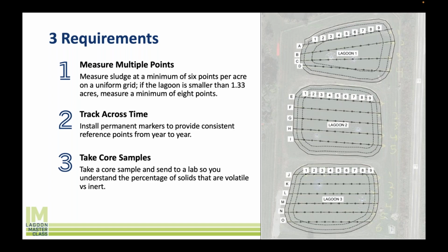Third thing is, when you do this survey, take core samples of the sludge. Okay, it's not good enough just to know how much sludge you have in your lagoon. You need to know what percentage of that sludge is the volatile organic component, the part that can break down, and how much of that sludge is your inorganic component, right? The inert, the stuff we can't break down, right? The non-volatiles.